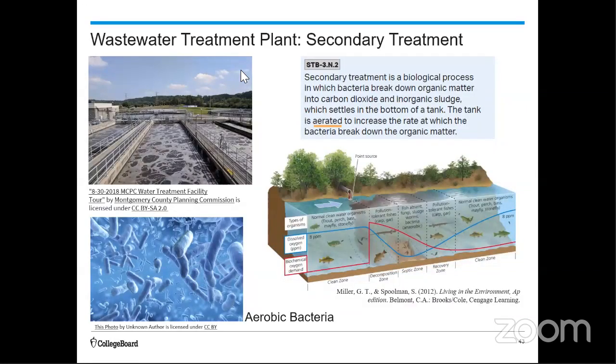Now, why do we have all these bubbles in here? That's really important to talk about, because if you remember from our conversation the other day on eutrophication, the point source pollutants coming into the stream is going to demand a lot of oxygen, because these microorganisms, these decomposers, really want a lot of oxygen. So what we see in this stream is the oxygen sags down, this oxygen sag curve, because the oxygen is being used up.